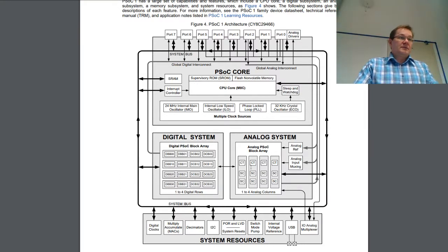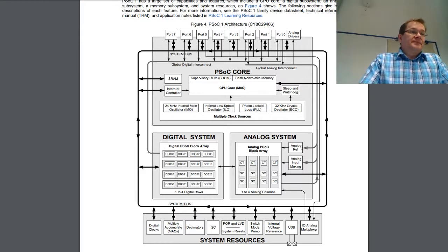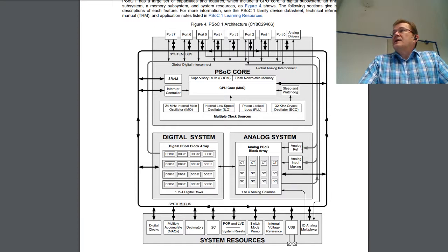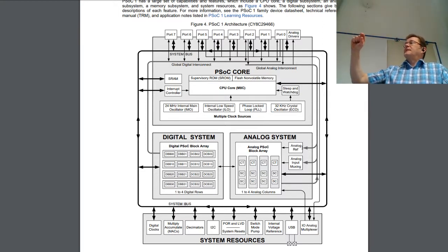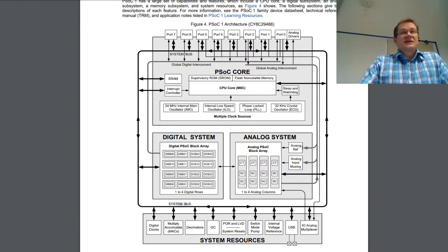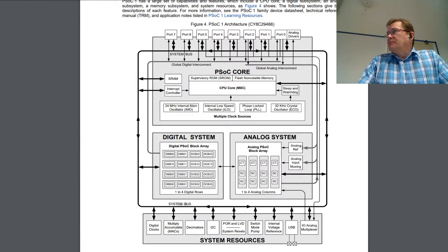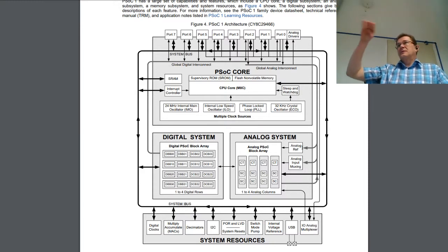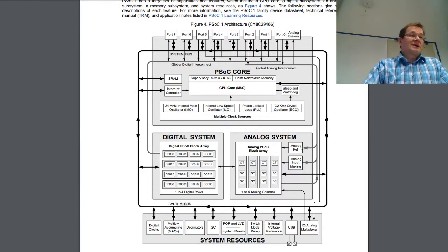Okay, and then it also has the analog reference bus. There's an internal band gap, meaning that it has a reference voltage and also multiples of that one, and a switch matrix, so you can run this analog system as unipolar or bipolar, biased to the reference levels.